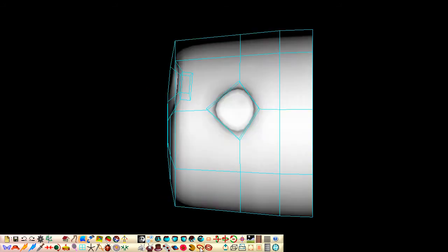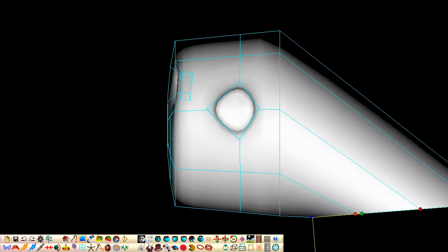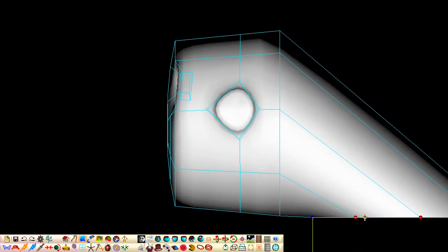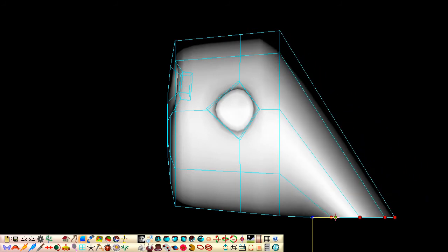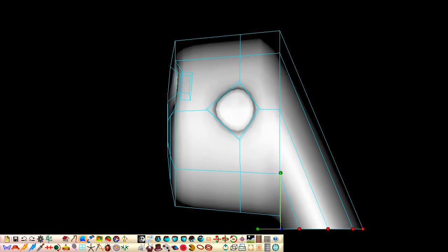To select a ring of control points, click this button and then click the ring. To change the position of the pivot point, drag the blue point. Drag one of the lever points to rotate the selected points around the pivot point. To squash the points, hold down the left Alt key while dragging one of the levers. To move the selected points, drag any one of the selected points and all the selected points will move with it.